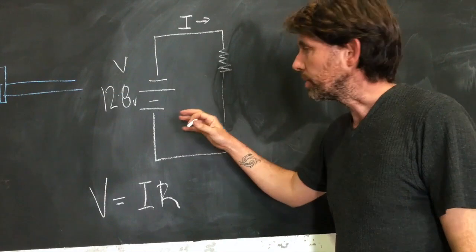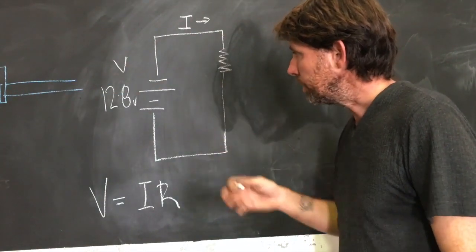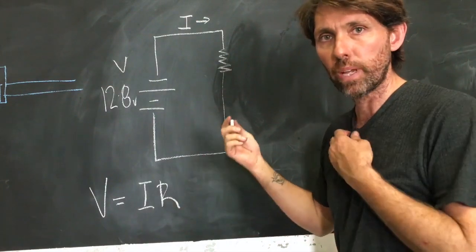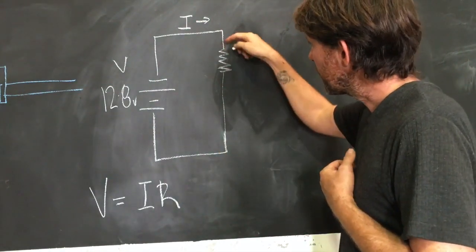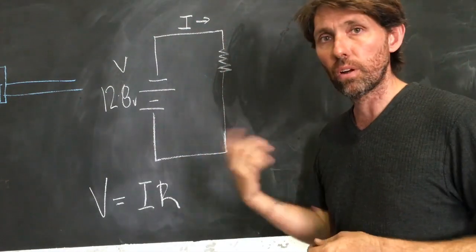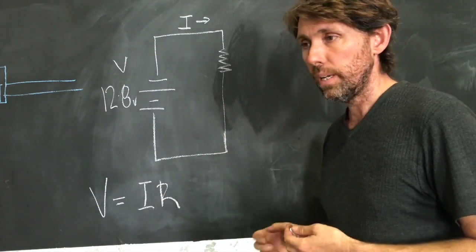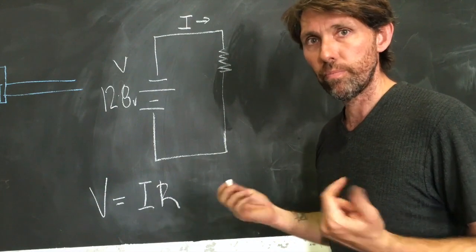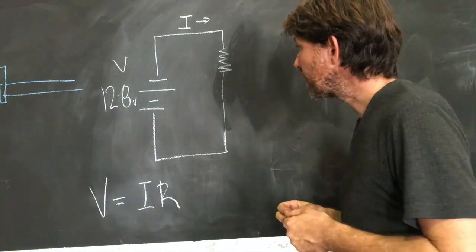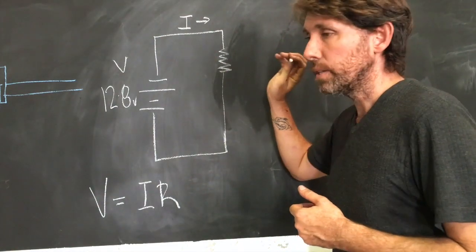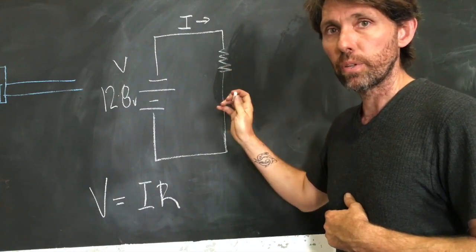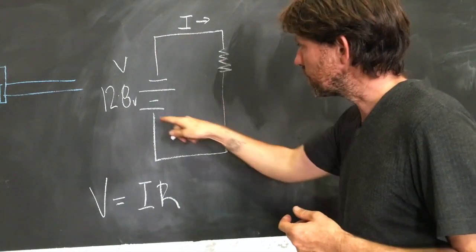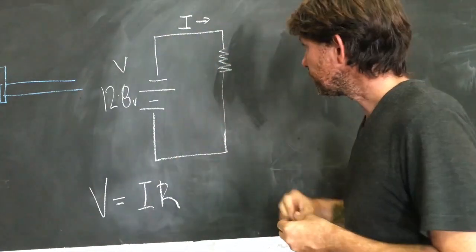In our simple circuit, once the current's flowing, we can start to measure how much voltage is dropping at a particular point. So in this part of the circuit, we've got this one little section that is a high resistance. That could be, say, a particular device on the circuit. It could be this dodgy connection we're trying to track down. But it's only once the circuit is actually flowing with current, it's complete, that we can start measuring the voltage drop across it. So we have this section complete, the device is on.